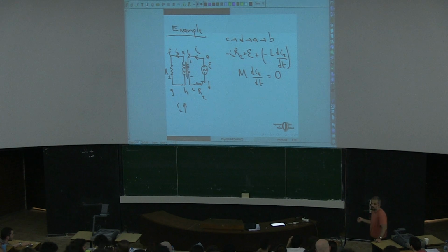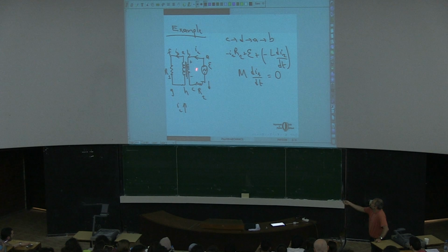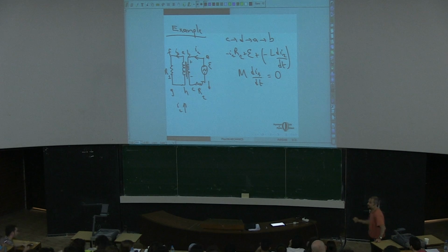it will behave differently. Because let's say if I1 is increasing, then due to the self-inductance over here, it will try to push a current in the downward direction. Depending on the wiring, it might push a current in the downward direction or the upward direction. So that is an information that is missing in the question.